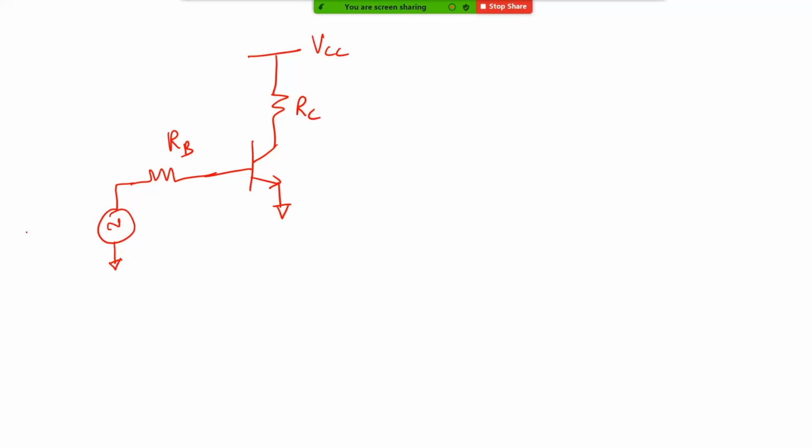All right. So now, we started off with a very simple amplifier, so let us try to do the small signal analysis for this particular amplifier. We said a simple amplifier looks something like this: VCC, we have an RC, and we have the same transistor, and let's say we have some RB, and we have the signal source here, VS. VS can be written as some capital VBE plus some VAC, or let's just call it a small vn.